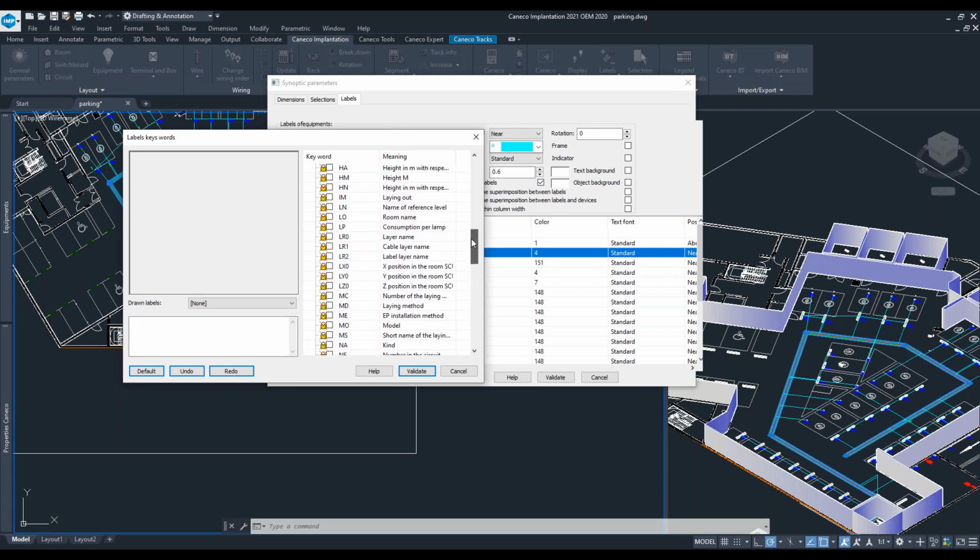Let's delete it. I want to have the circuit information. It's not important for the EV charger because it's every time the first one, but I can also define the reference marks for sure. The number in the circuit is maybe important for fire detectors, for smoke detectors, because in that case it's important which position they are in, or for emergency lighting. Also there you can define it, and we have full information about the circuit.